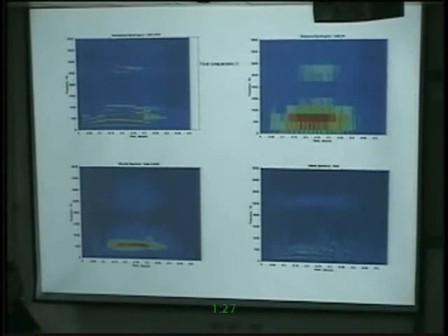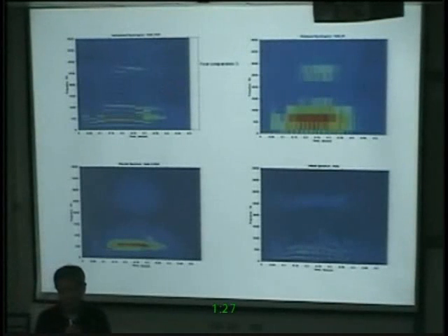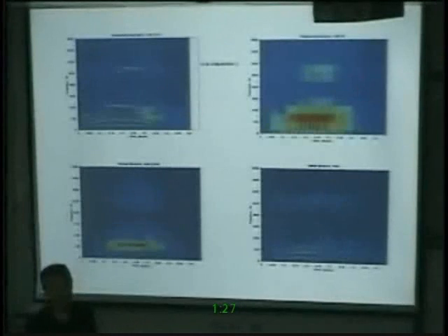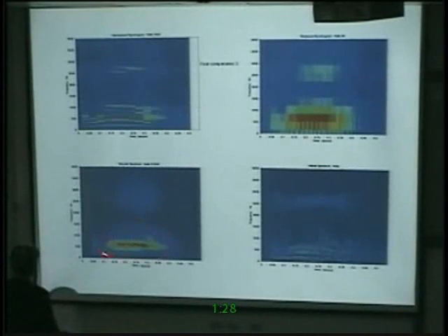The fact that you cannot determine time and frequency to arbitrary precision is called the uncertainty principle. And the uncertainty principle is the consequence of integral transformation. And Fourier is an integral transform. So you cannot determine time and frequency both very accurately. Now you look at this. This is wavelet. A wavelet compared to these two looks much better. But then you compare this with the Hilbert, it's again different.